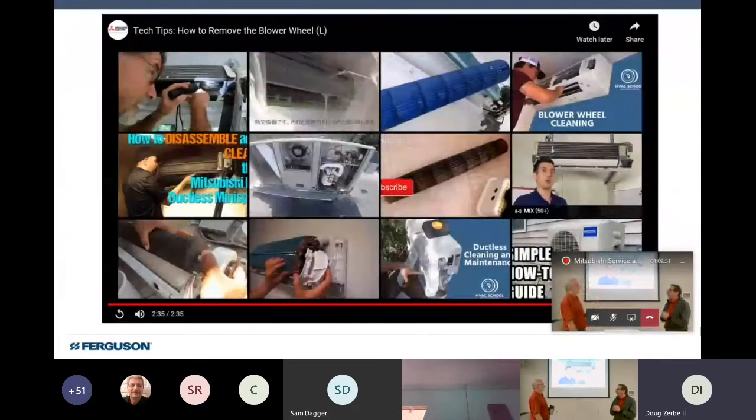Right, he definitely makes it look easy, doesn't he? And quite honestly, it may not be as easy as that. I've got a tip there too: don't remove the screw from the motor shaft all the way, because if you do, you'll definitely need a magnetic tip Phillips head screwdriver to get it back in.